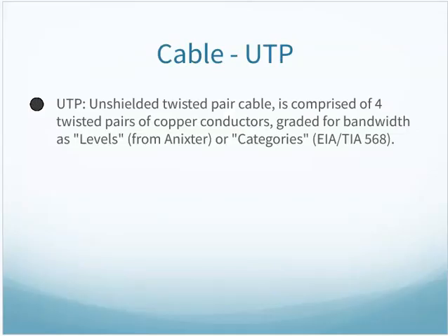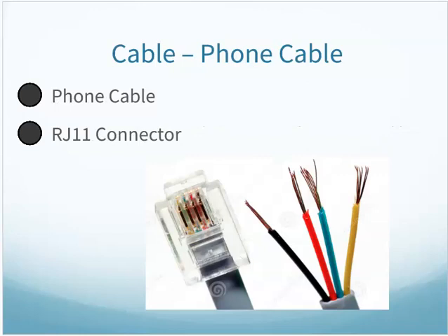So, looking at unshielded twisted pair, as we said, categories were developed to identify what it would be able to support. Refreshing these for you again, we started off with phone cabling, non-paired flat cable. That was good for 14.4K of bandwidth in the days of dial-up modems.